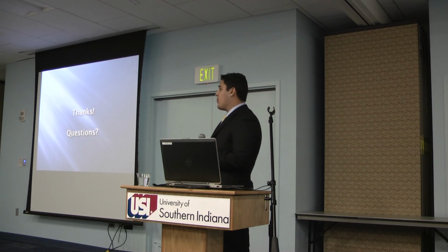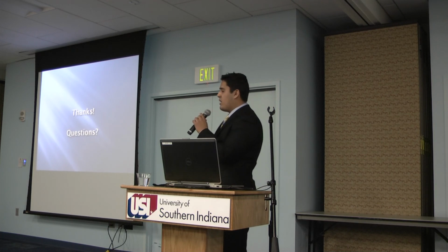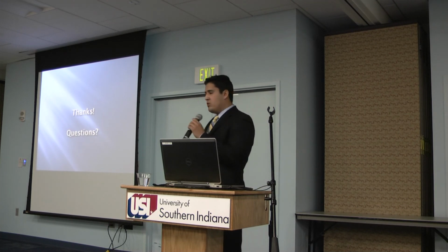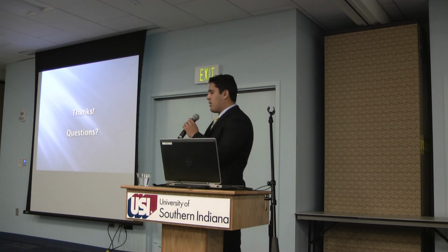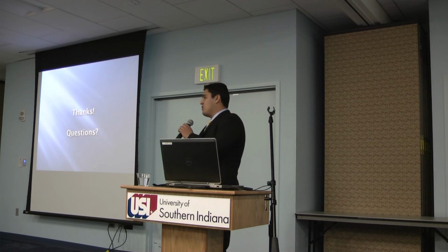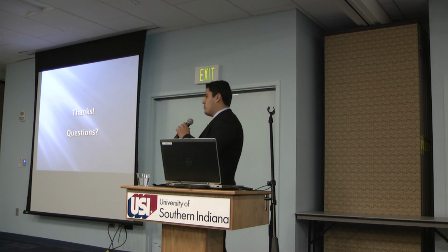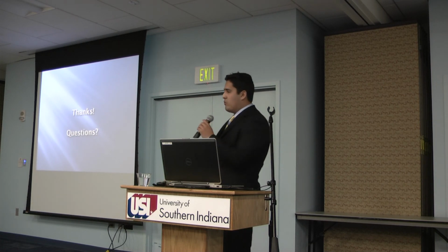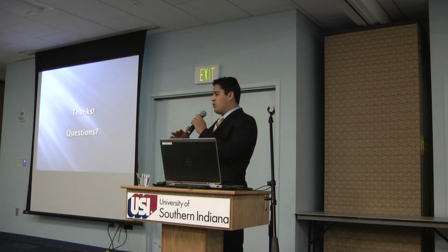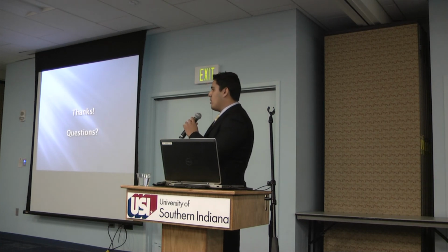And does your dosage of the urea, phosphoric acid, does that vary with the COD? It sure does, because the urea addition, I don't think I mentioned it, my apologies, controls the nitrogen, which is a protein or like a vitamin for the microorganisms in order to have a much more stable system, and also the phosphoric acid will be a phosphate source for them. So the higher the number, we have to add a lot more chemical to it in order to have a much cleaner water. They need more food or nutrients per se in order to clean the water.